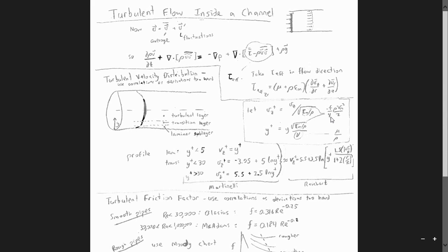So, this is the correlation that is modeling the situation with this theoretical application of the conservation of momentum being satisfied, where we're accounting for velocity fluctuations. Those velocity fluctuations are represented through an adjusted shear stress, causing the turbulent core to be relatively flat.